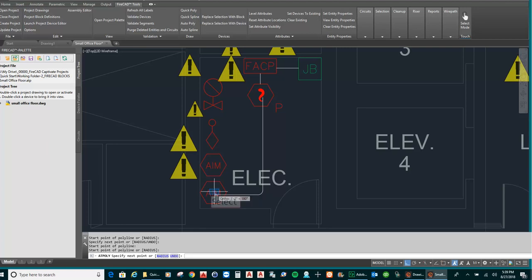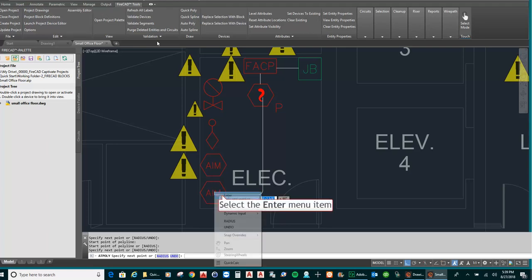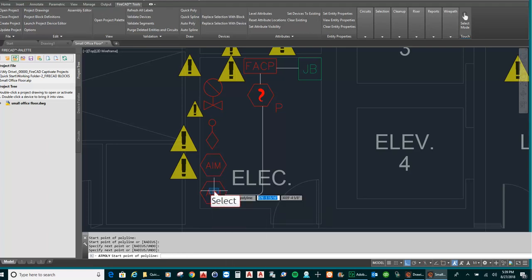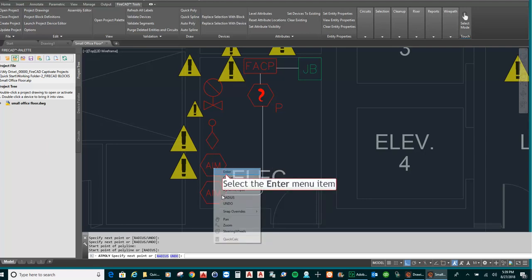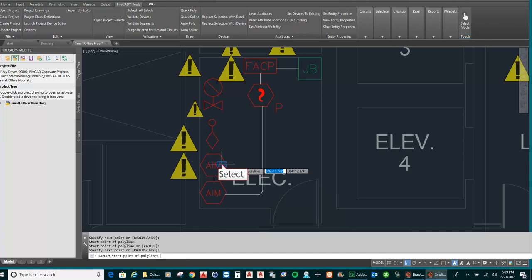When we use Auto Poly, it's a good idea to set ortho on so that your polylines are nice and neat and orthogonal with a filleted radius where they bend. Again, the lines trim automatically at the bounding edge of the block when we terminate the command.